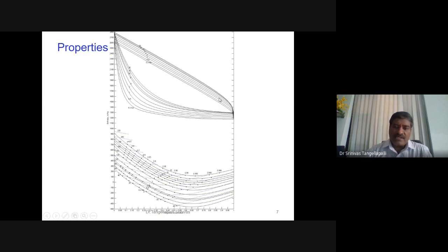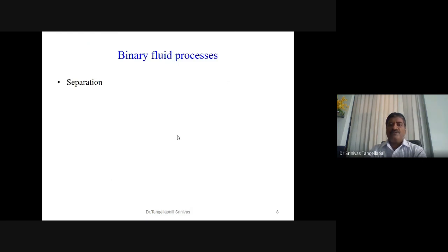That is called an isotherm. That means the temperature of liquid, temperature of vapor and temperature of mixture are all the same. How to locate the state of the mixture? From the mixture concentration we draw a vertical line. This vertical line and the isotherm meet each other. That intersection point is the liquid-vapor mixture state, which we are going to use in the process.